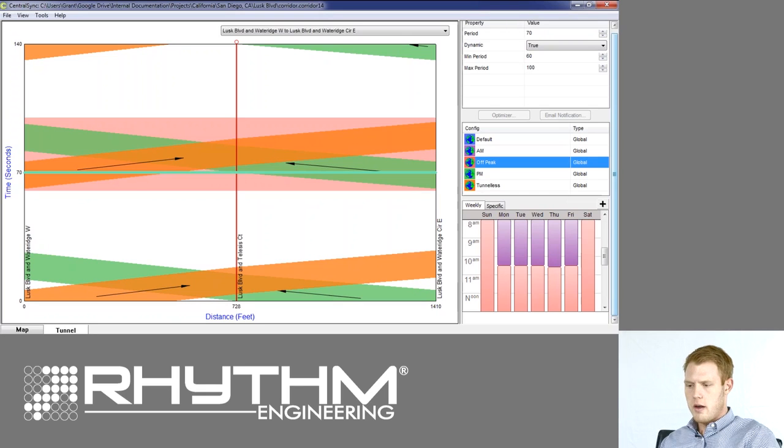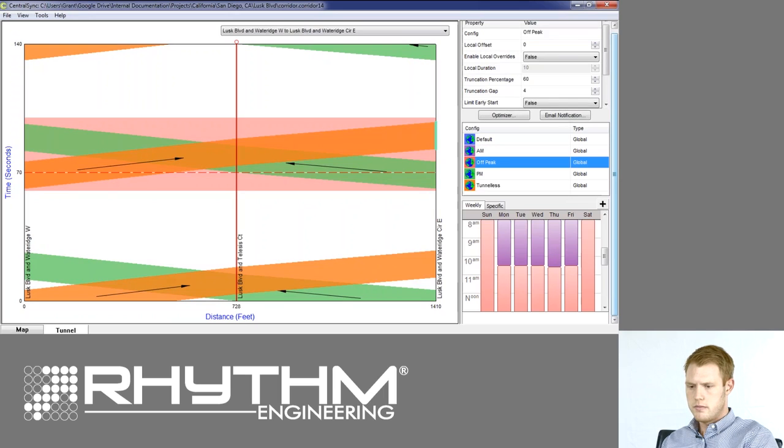From the time-space diagram, you can also see the tunnels for each respective direction, as well as the non-tunnel time. So if you hover over the white space between tunnels, you'll see the non-tunnel time, which is how much time can be allocated to any movement outside of the tunnel phases. So InSync dynamically allocates green split time based on the queue and wait time it sees on all approaches.